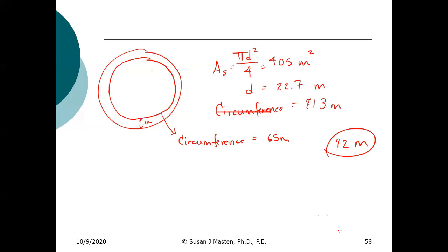So what that means is, the water's entering from the center, and it's going to flow over this weir into this basin. Given that, we can either have a weir that goes all the way around but is only notched on one side, or we only need half the circumference and we can notch it on both sides.